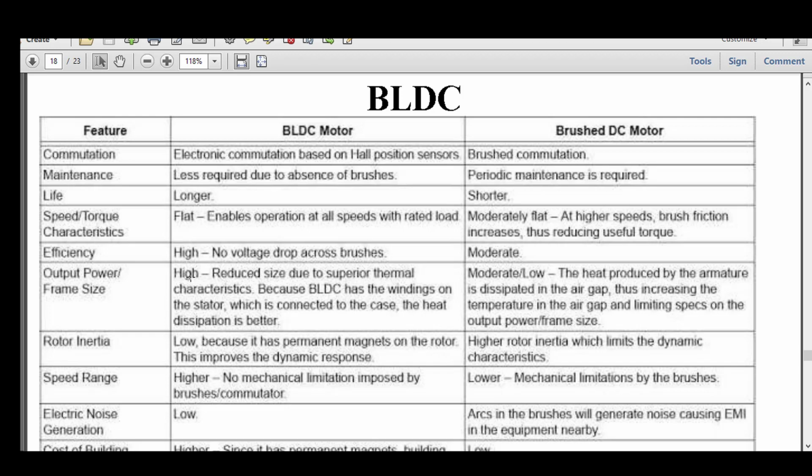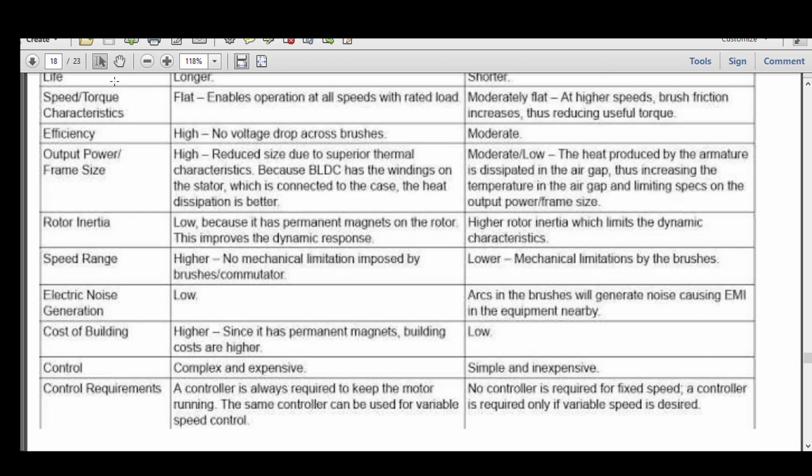So all these are advantages of a BLDC motor, and its speed can also be higher than the brush DC motor, because in brush DC motor higher speed needs more advanced commutation techniques, but in BLDC motor the commutation is done through electronic switches, so it is almost free from the hassle of sparking across the brush.